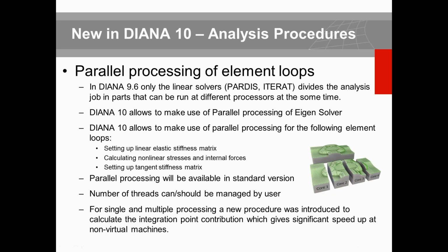Quickly, I will go through the new and very important development that we have for parallel processing. What we had before was for the solver, and that was for the Pardiso and iterative solvers. Now parallel processing is also available for the eigensolver. And in DIANA 10, you can literally do parallel processing over the elements to assemble your linear elastic stiffness, to calculate nonlinear stress, strain, and internal forces, and to get the final tangent stiffness matrix.